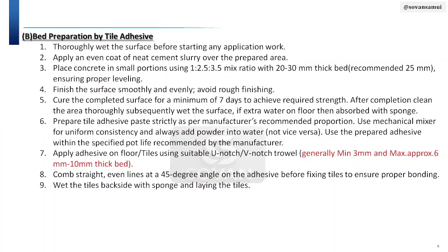And next, subsequently, we are discussing the second point, that is bed preparation by tiles adhesive. So again the same concept will happen, that is thoroughly wet the surface before starting any kind of application.